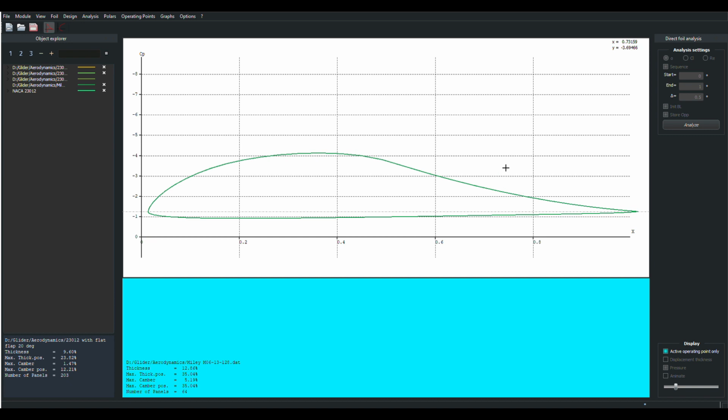And I know that the 23012, just in general without deflected control surfaces, does pretty good all the way down to 500,000 on the Reynolds number, and because I was a bonehead, I designed myself into a corner where the tip chord was 24 inches and I got myself down below 500,000. That was just, we'll call it what it was, stupid.